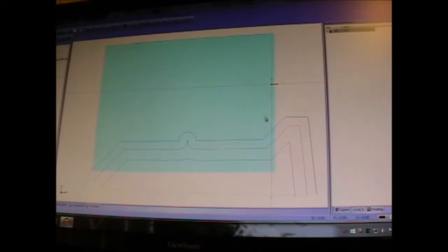Okay, so here is a view of the geometry. This is the diameter of the work. This is the end here on X0 level with the end, Y axis 0, the center line of the part, and that way the geometry is offset to give us the correct numbers. Obviously the X and Y numbers and Z numbers won't be correct, but the actual information, the values will be correct.